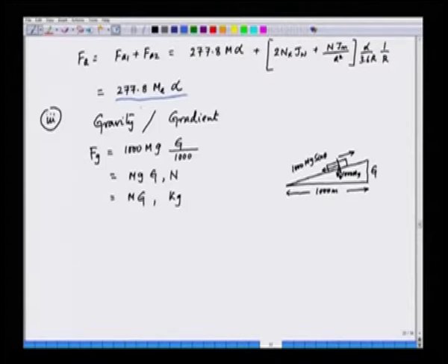That is not just the mass in ton, but it is something higher than that, that can be calculated in the following formula. We have to know the moment of inertia of the wheels, the number of wheels, the moment of inertia of the rotating or the driving motors, the number of driving motors n, the gear ratio a square here, and then the radius of the wheel. So, this expression will give us the effective mass Me of the locomotive.